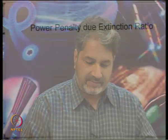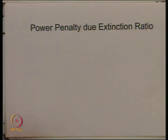Here what we are saying is that when the 0 level of the data is transmitted, the optical intensity is not 0. Now, there are certain reasons for that in a practical system. Firstly, if you recall, when we talked about the optical detectors, we had something called the dark current.